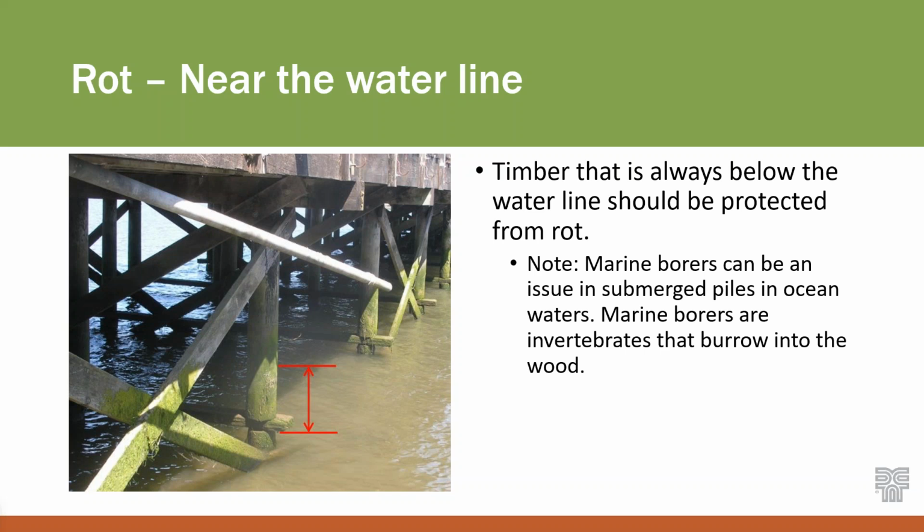Waterline is another good place to look for rot in timber. It's that wet-dry cycling that is typically a big driver for it. So that's a good place to look. If you have a tidal area, you might have some of those issues, or near a stream where you have the up and down of the flows, getting the pile wet and allowing it to dry.